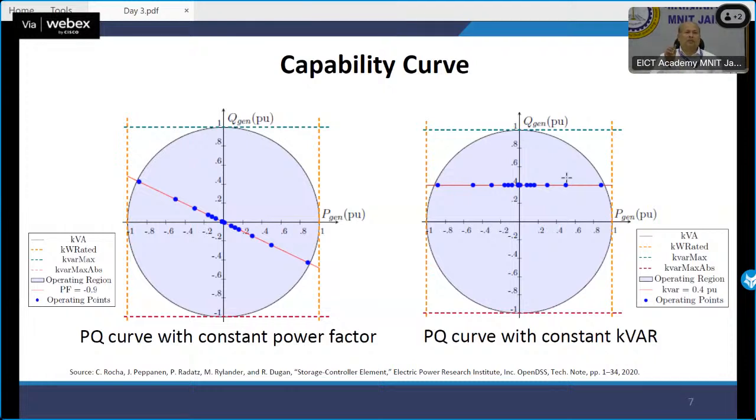All right. Different points will give me different P and Qs, and you have to decide how much P and how much Q you need at a given operating point. So this space is open to you, and you have to decide so that in a given period of 24 hours or maybe half a day, you can optimize your complete charging and discharging cycles.